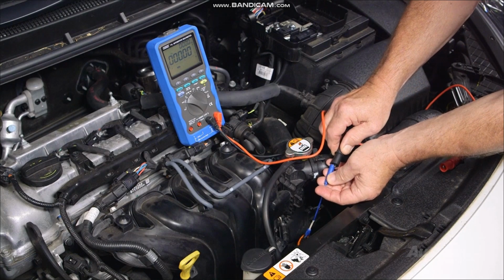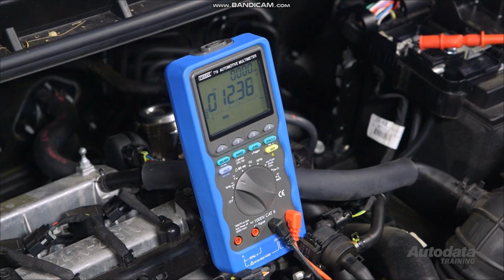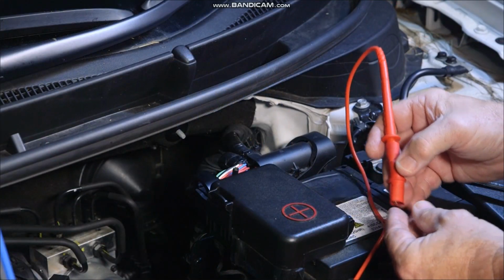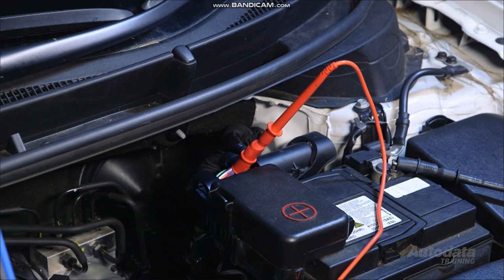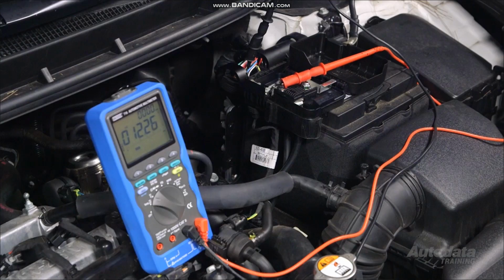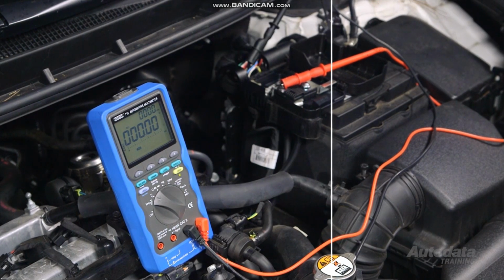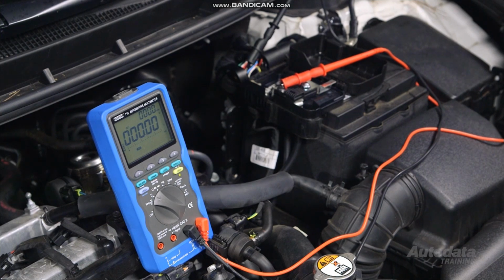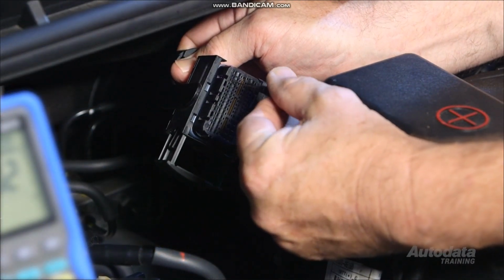Connect the meter between the sensor signal connector terminal and battery positive. You should see battery voltage. If there is no voltage, then back probe the next connector in line, which in this case is the ECM, and retest. If you now have voltage, then there is an open in the harness on that circuit. Still no voltage would indicate an open circuit within the ECM or the ECM connector. Test the suspect terminal for corrosion and terminal tension. If no fault is found here, replace the ECM.